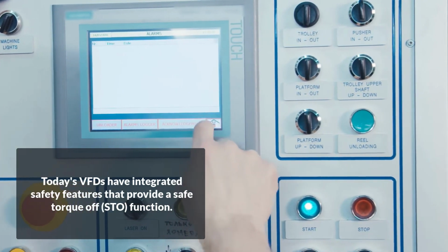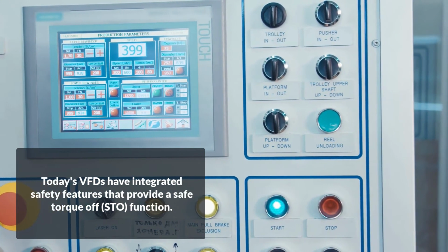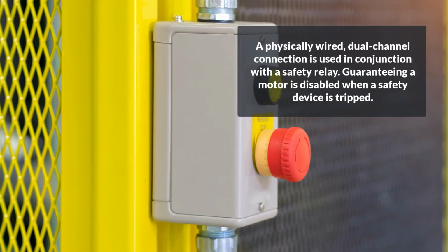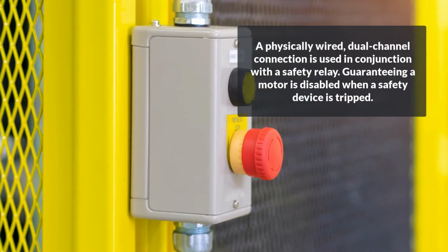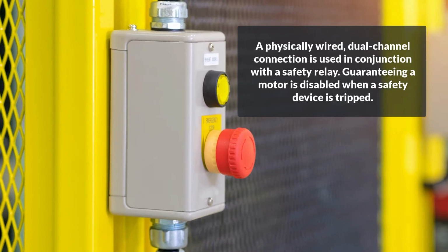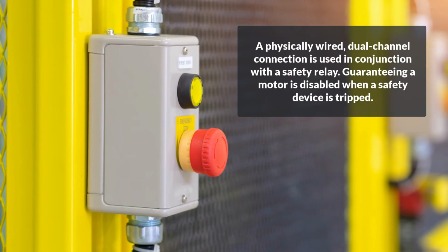With STO, the drive is prevented from producing any torque generating energy. When this feature, a physically wired dual channel connection, is used in conjunction with a safety relay, there is a means by which to guarantee that a motor is disabled when a safety device is tripped.